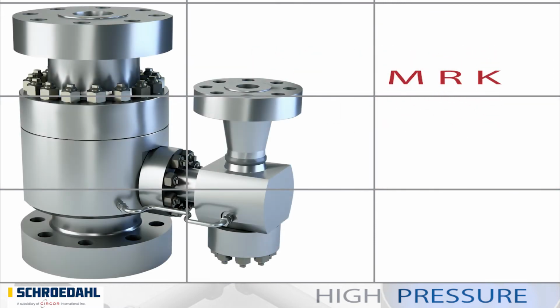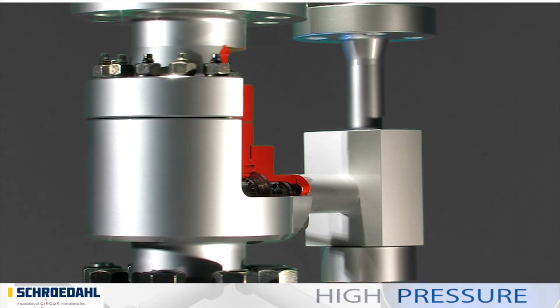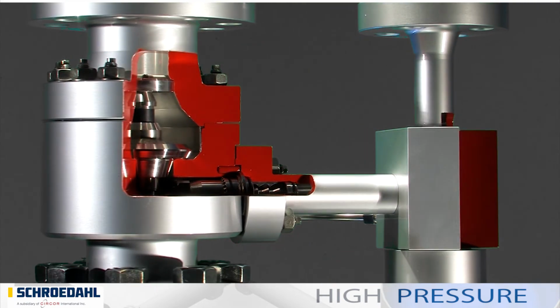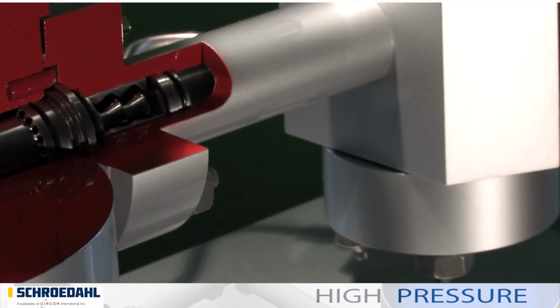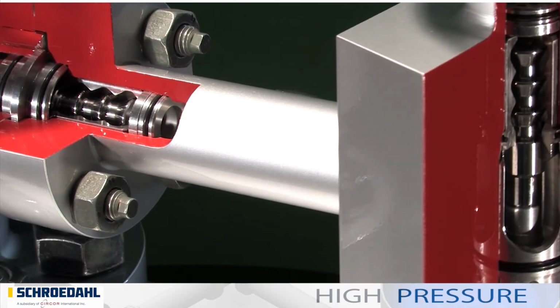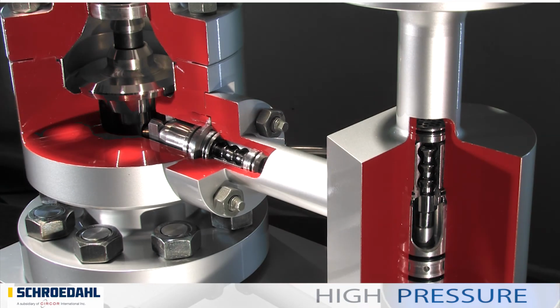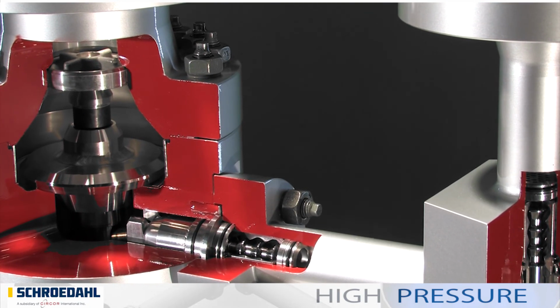MRK is the valve for the absolute high pressure and partial load range, and is particularly suitable for speed-controlled pumps. The MRK is a further development of our successful TDM range of high-pressure valves. It combines a cost-effective approach and a highly refined technology. Pressures up to 500 bar can be reduced by the unique two-part bypass design with 7 to 9 regulated stages. This is achieved via the main non-return check valve with minimum energy loss.